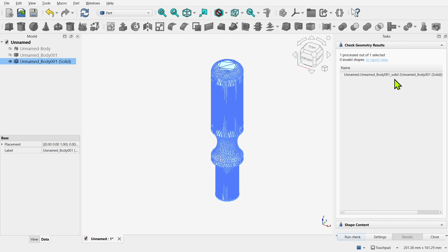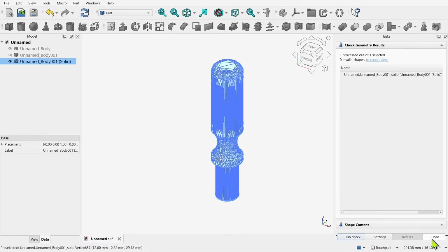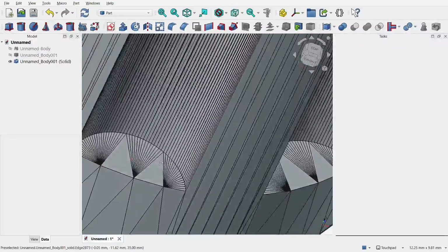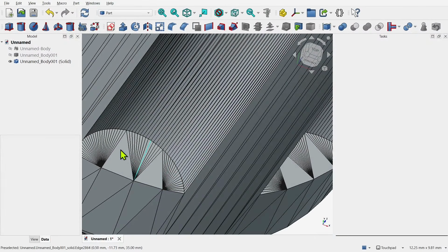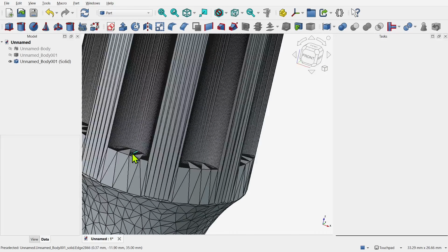As we can see here, if this check fails, then the mesh may need external repair through tools such as Blender or something like Mesh Mixer. Finally, we may need to refine the shape. If we look at this shape, this is a planar face, and we can see we have all of these triangles in here, which can be refined down to a single face. So we can merge faces all on the same plane.